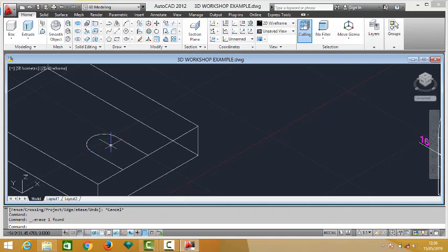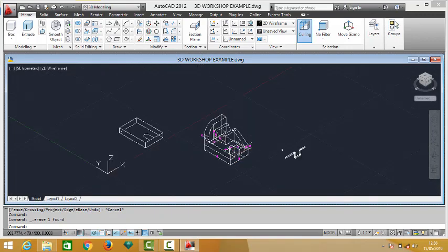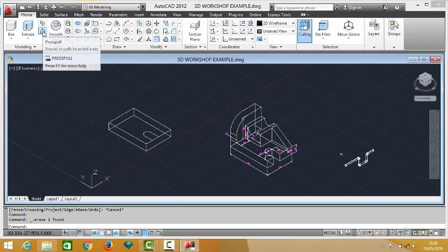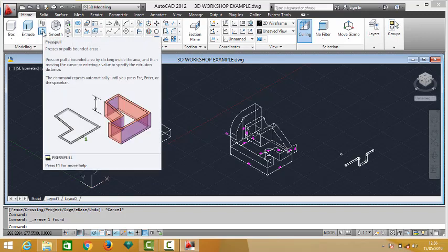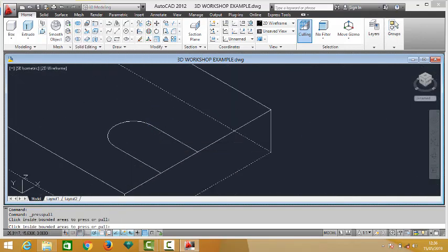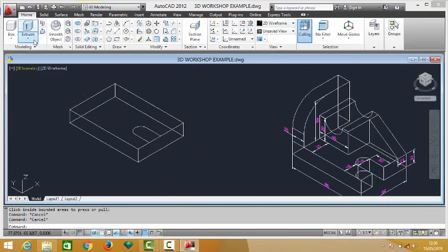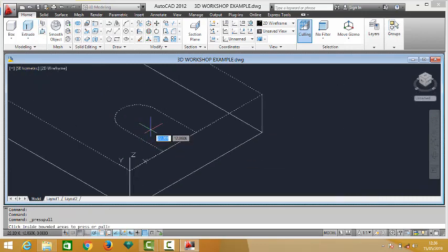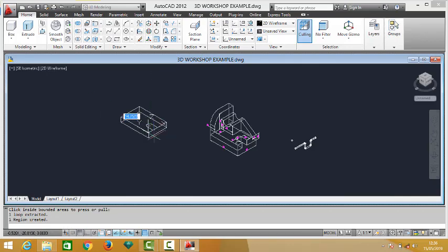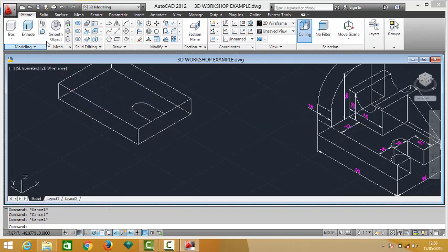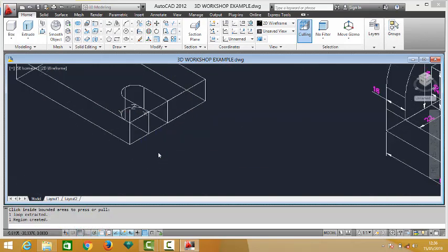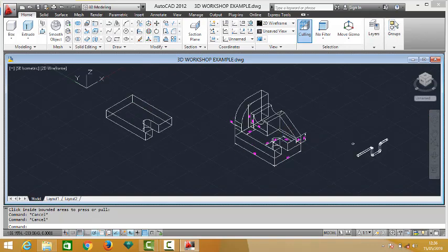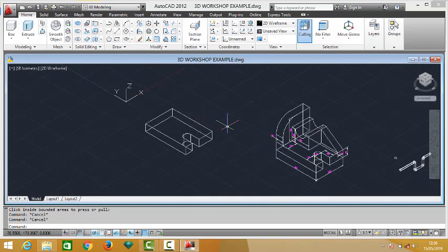This I can delete. So I will now need to pull this cut down by using press pull. So I come to press pull. Remember, we have treated all of this while we are treating the entire tools in this 3D modeling workspace. So take here, I take on my press pull again. Okay, I pull down, and that is it. So I've succeeded in creating this opening here.